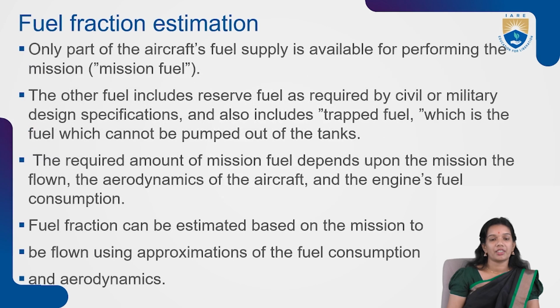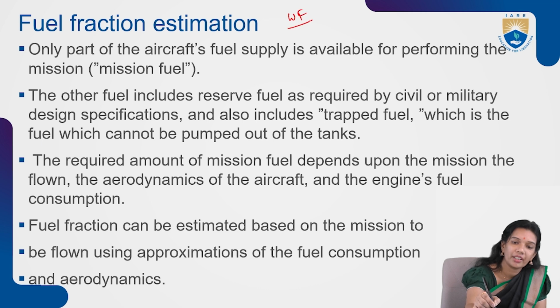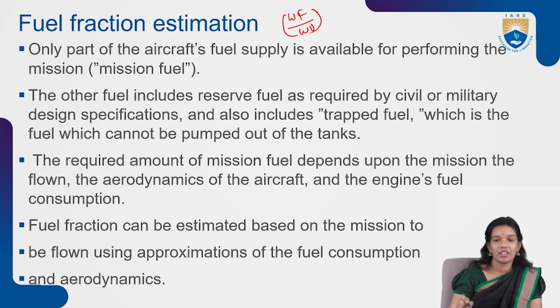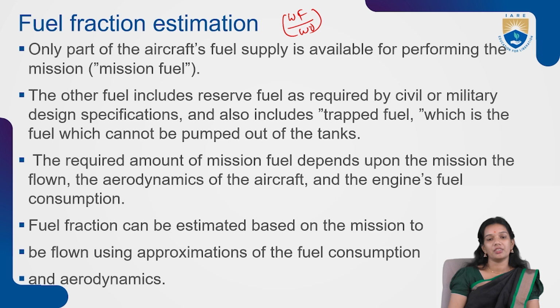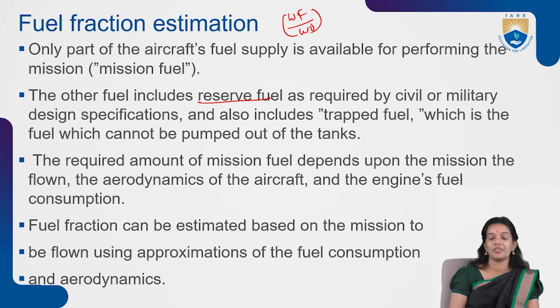Then we have fuel fraction estimation. We said it is WF by W naught. Now, when I say fuel fraction, there may be different types of fuels. One is mission fuel, which is the aircraft's fuel supply available for performing the mission. But apart from this, we also have the reserve fuel, which has been reserved for emergency purposes. For example, if the airport is closed, or if I don't have a runway